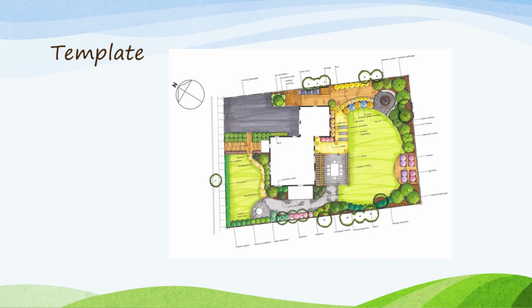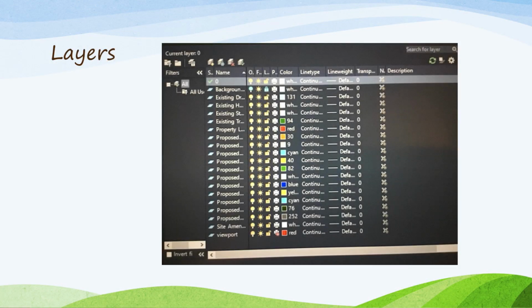To begin our project, we added a template to follow for our drawing. This was provided by our professor and gave us a background for us to transcribe the design onto AutoCAD. This template, however, was not to scale when we added it into our model space, so we needed to use a different set of tools. We used the scale tool and measure tool, along with information from our professor on the proper size of our template, to bring this background into a 1-to-1 scaling. Once we had our drawing scaled, we could begin drawing.